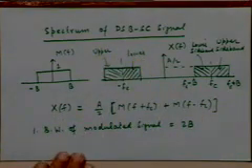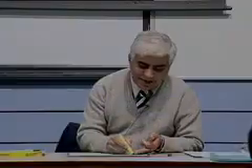Yes, please. So in the original signal which I'm having, if I take only the right part of the signal, the positive part, do I get the whole information? The trouble is, for a real signal I can't get rid of this. The real signal implicitly has a negative frequency component because it's just a mathematical notion. I can't get rid of it. The only way I can get rid of it is by converting it to a complex signal. But effectively my right part is having the whole amount of information. So when I'm putting it in this part, I'm having a bandwidth of 2B, but that bandwidth of 2B is having only the information which is originally present in the right part. So I'm not getting any additional information as such.